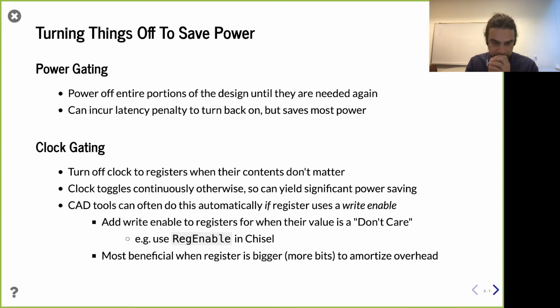If you're wondering in the back of your mind about the circuitry added to do clock gating and detect the write enables, doesn't it have some amount of overhead? It definitely does. But normally in our designs we have not just single-bit flip-flops, usually registers of 32, 64 bits, whatever. So we're able to amortize that single-bit signal over those many bits, and usually it's actually not that bad.